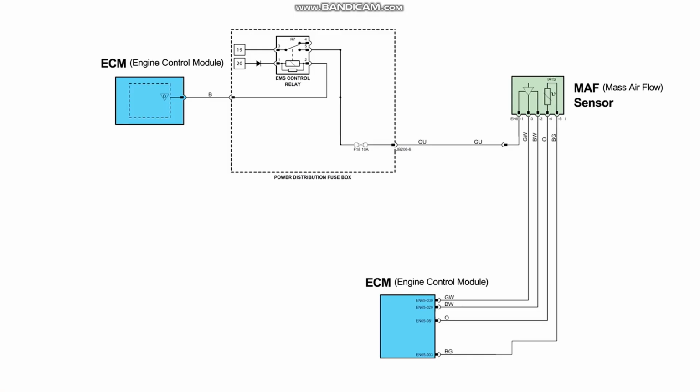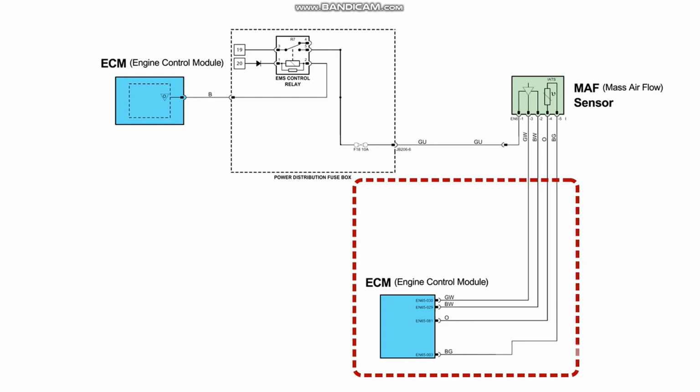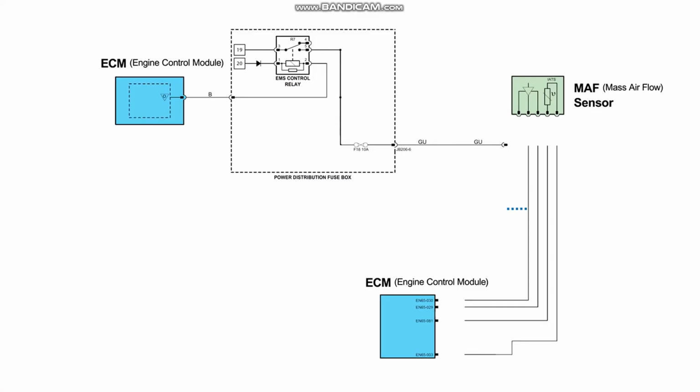This could be located in the harness or the module. Turn the ignition off, disconnect the ECM, and check your reading again. If the ground is still there, then the signal wire must be short to ground. You could now go to any connectors in the circuit and repeat the test to try and isolate the fault to a particular part of the circuit. If the short to ground is now gone, the fault must be the signal wire is shorted to another ground coming from the ECM or the ECM itself.